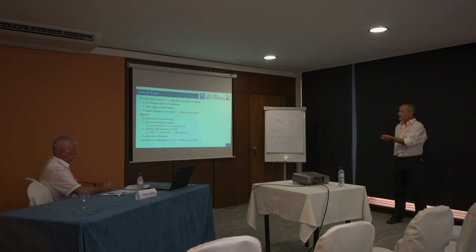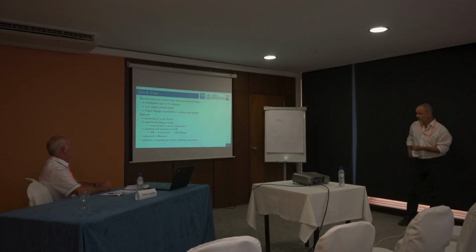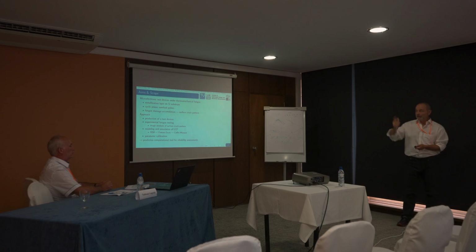Again, microelectronic test devices under thermomechanical fatigue. This means we have a silicon substrate with a metallization layer on top. This is subjected to thermomechanical loading, and we look at the fatigue damage accumulation, but now on the crack pattern on the surface of the copper. So we do not look at the cross section, but now we look on the crack pattern on the surface, which is visible.